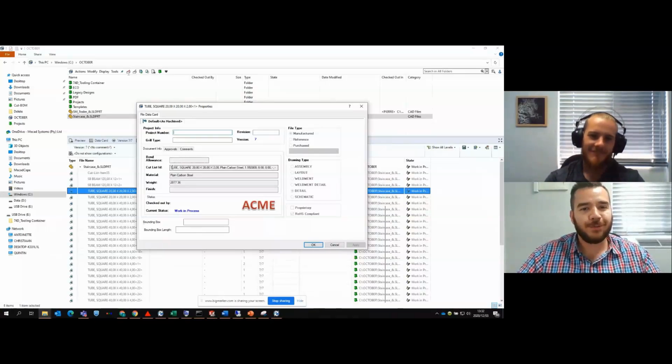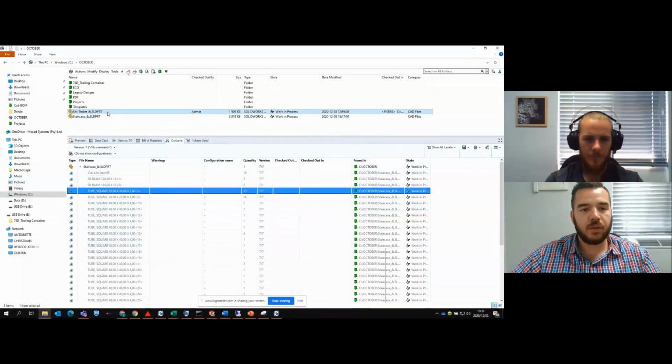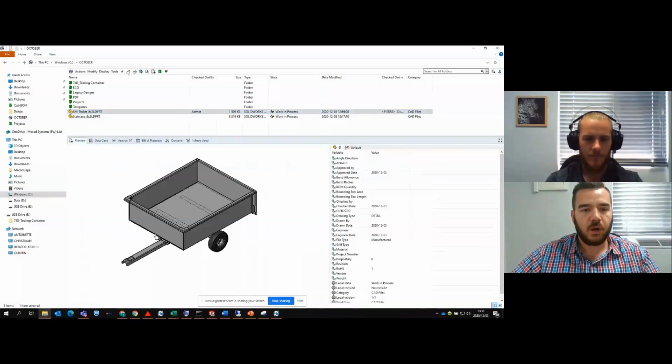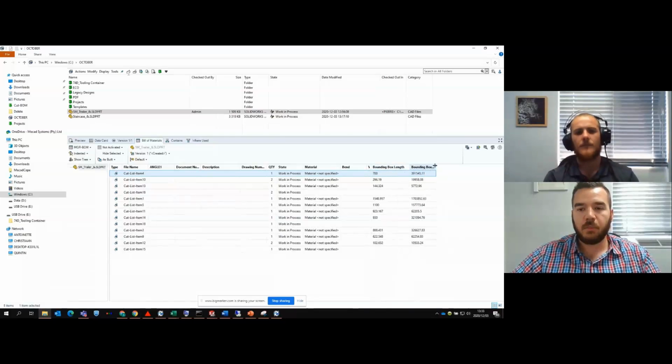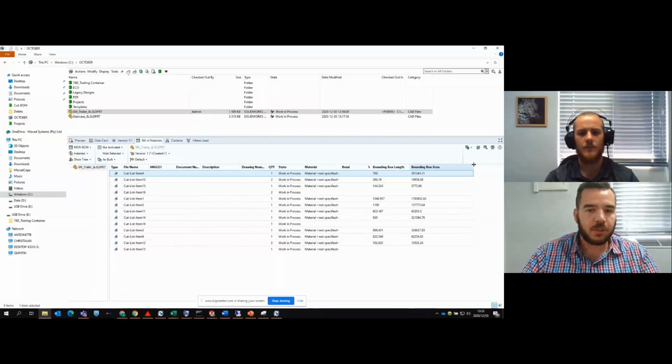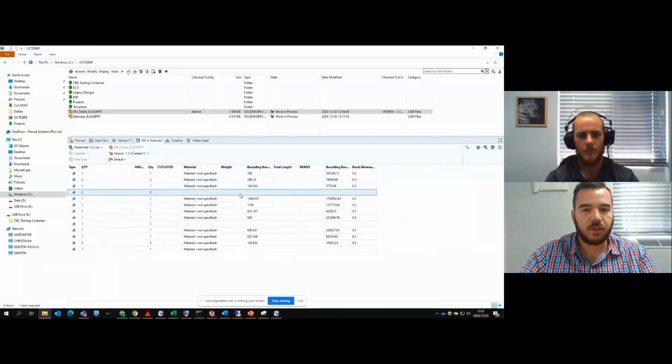So I know your webinar is for the Weldments, but just as a sneak peek, you can do exactly the same for sheet metal parts. Sheet metal parts will also have their own specific ones. So like this, where I have a sheet metal part, I can again look at the Cutlist items for it, the different materials. And in this example, maybe I've got the bounding box. That's maybe important information in my sheet metal parts. Now in 2021, just to emphasize, you can show all of that information within our bill of materials directly in SolidWorks and in PDM.